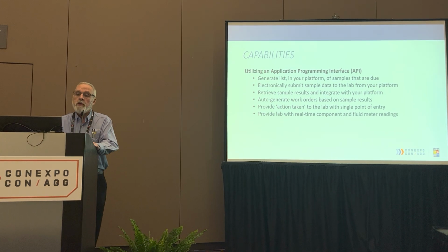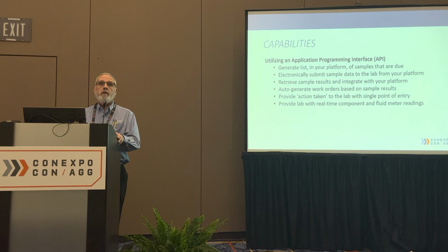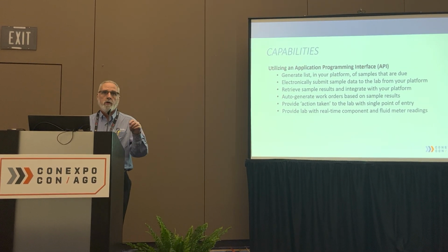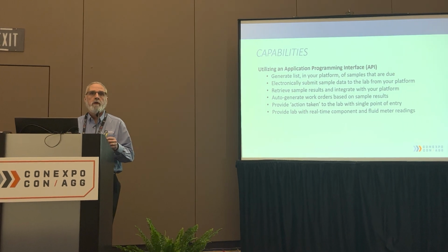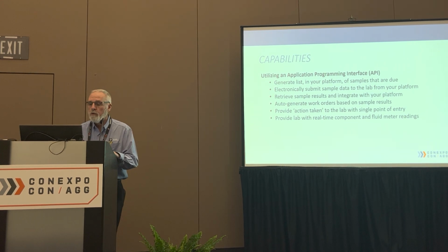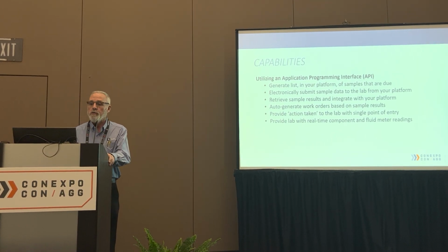I mentioned this earlier, provide the lab with real-time component and fluid hours. If you're already capturing that, either from your telematics, or it could just be an oiler's report when they fuel the equipment, they're writing down those hours and you're entering those into your CMMS. Now you can feed the laboratory with that information directly as well.